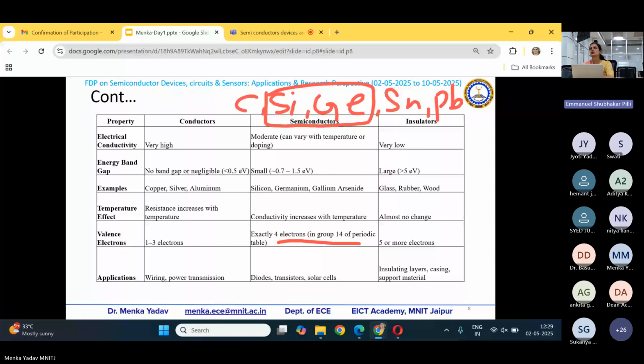Carbon is generally not used as a semiconductor in electronics because it has a little bit higher band gap compared to silicon and germanium, and the mobility is a little bit lower. So it is not going to give us good enough current. But yes, there are many electronic applications like thin film screens and foldable screens in which carbon and related things are used as a semiconductor material. And most widely we'll be using silicon, germanium, or maybe compound semiconductors. We'll come to that, what the compound semiconductors are and all.